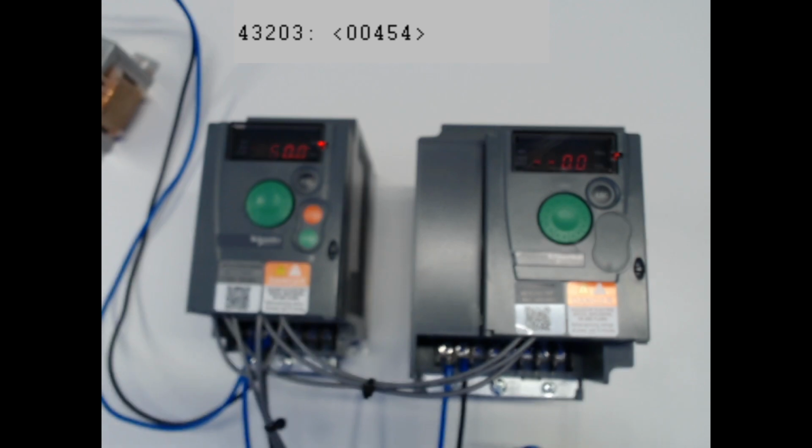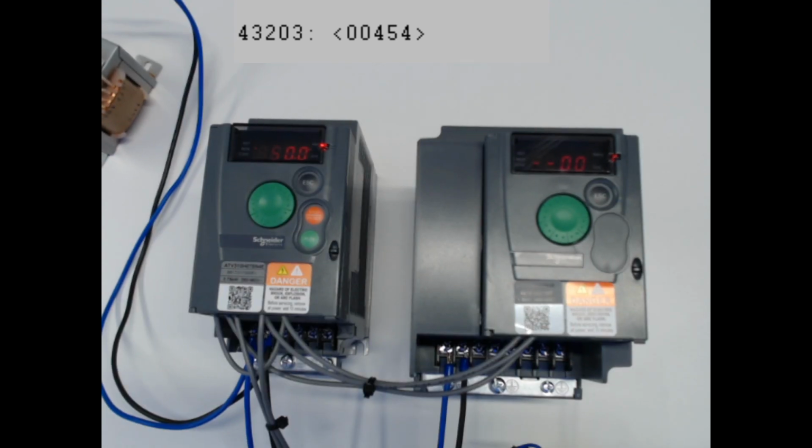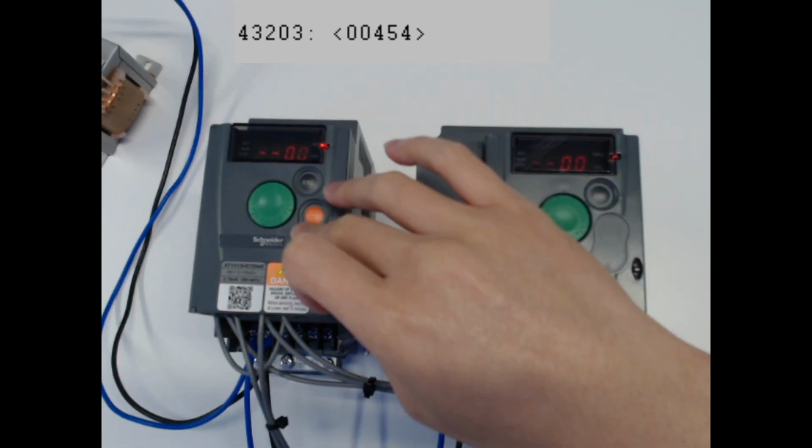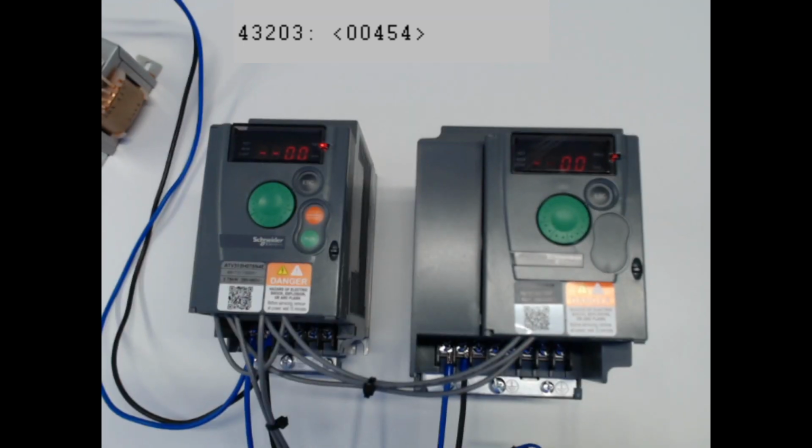Okay, so look over here. Now I am going to press reference. So if you can see the flickering, it shows 50.0. It means that my PID set point is at half of my AI value, at 5 bar. So now I am going to pretend that I have something in the manifold. Now it is 6.29 bar, which is above 5 bar.